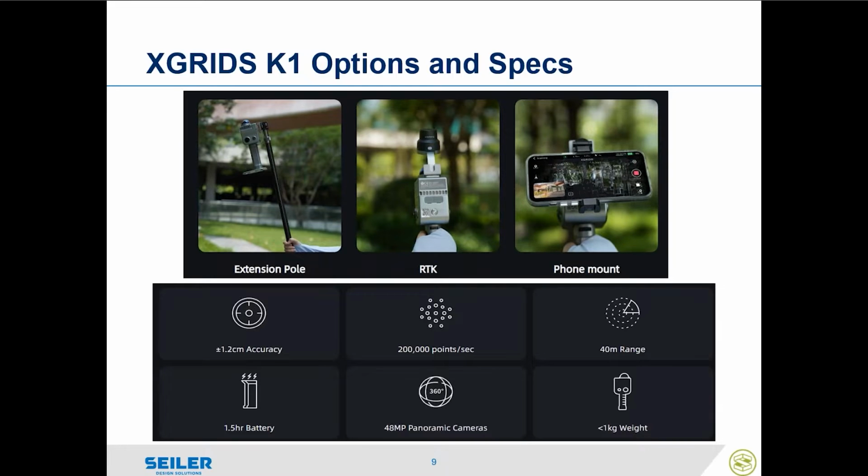It also has the ability to tie into an NTRIP with an RTK. So as you're scanning your building, you can start along the outside and take the exterior scan. Use an NTRIP like Kentucky CORS or MoDOT CORS as your correction source, and get real-time kinematic. That means your scan is going to be geolocated in real geospatial coordinate systems. As you move indoors, then your interior scan is also going to be tied into that same coordinate system.